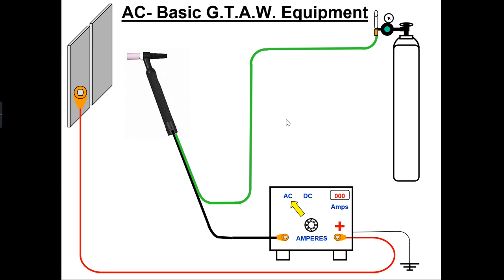The goal would be in most cases to be somewhere between 25 and 35 cubic feet an hour coming out of the end here. Could get much lower for something we call micro TIG, but normal operations 25 to 35. Remember, this is something for the welding engineering team, but the smaller this cone is, the lower the gas needs to be, because we never want to create velocity. So we have our control and we have a feed going to it.